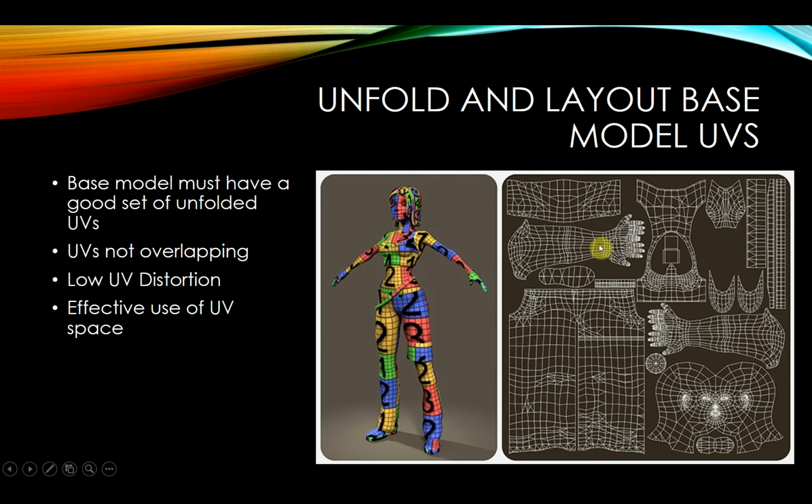For this, certainly if we're planning to use displacement maps, we don't want to do that. Okay. For general painting in Mudbox, that's not so much of a problem. But if we're doing things like normal maps or displacement maps or bump maps, i.e. any kind of maps that are going to add detail to the, I want to say the geometry of the mesh, but that's not quite right, but are going to shape the geometry in some way, you can't have overlapping meshes. It will cause you all sorts of problems. Okay, so yeah, avoid that.